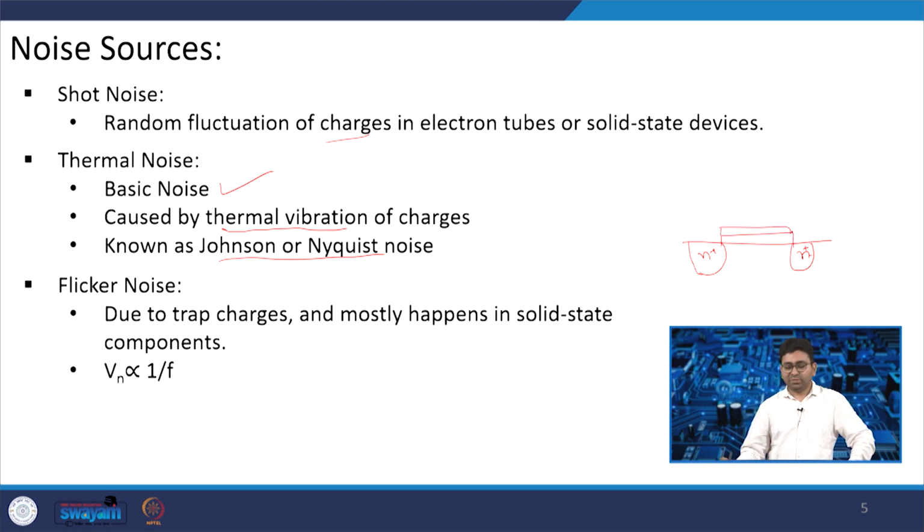Now, in the silicon oxide, an insulator SiO2, if there are some traps, then due to these trapped charges there is a noise, and this noise is mostly dominant at very low frequency.